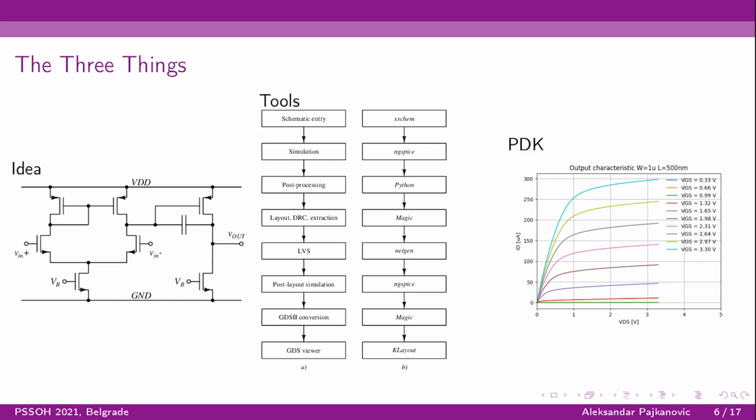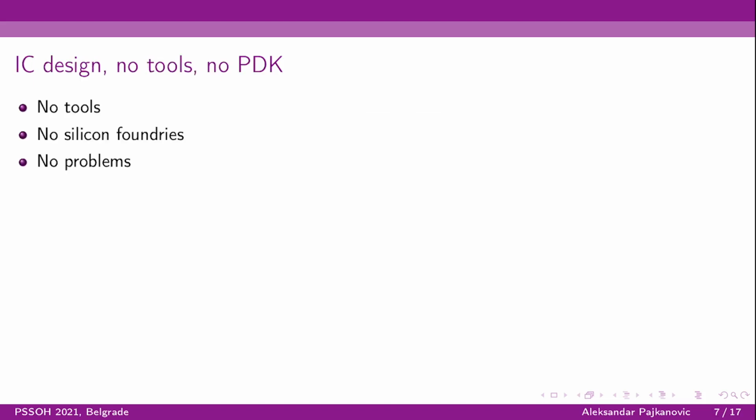And then the PDK is an abbreviation of process design kit, and that's basically the collection of the data related to devices that the factory can fabricate. This contains models and information of the devices such as transistors, diodes, resistors, and so on. When we work on an idea within the tools to solve a problem, we have to use this information in order to make our results achievable and our design manufacturable.